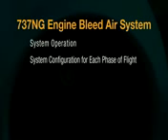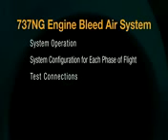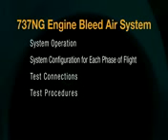Since the log report will tell you when a problem occurred, knowing what the system should be doing during that particular phase of flight will help isolate the fault and give you a better idea of what tests need to be run. You should also know where and how to attach the test equipment, run some of the more common tests, and interpret the results of those tests.